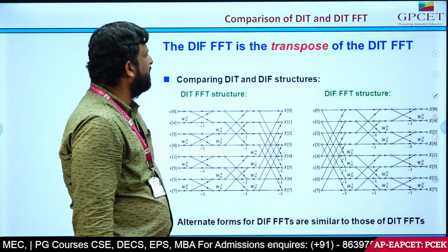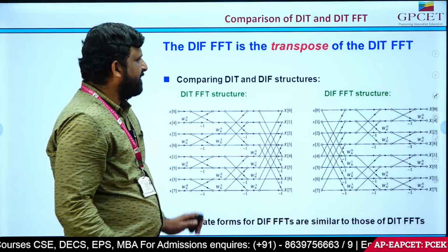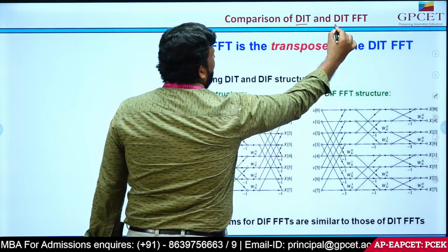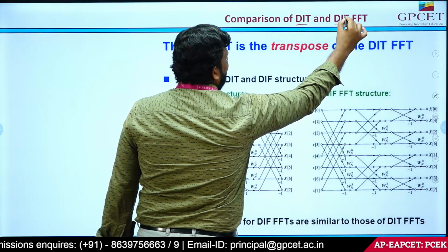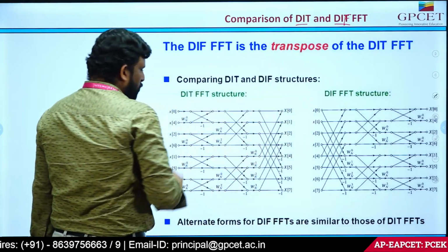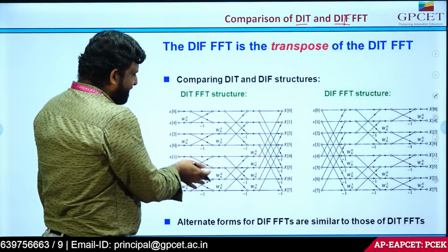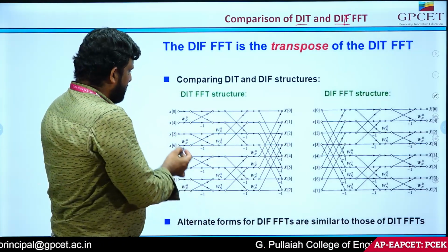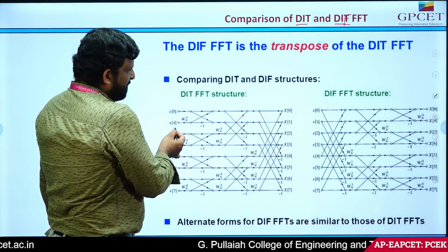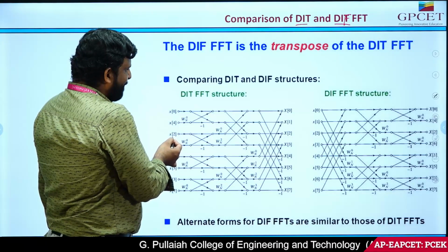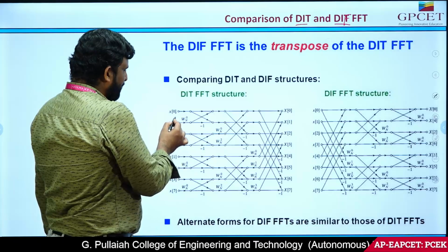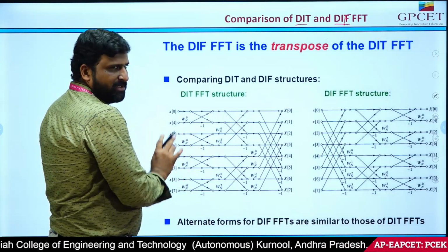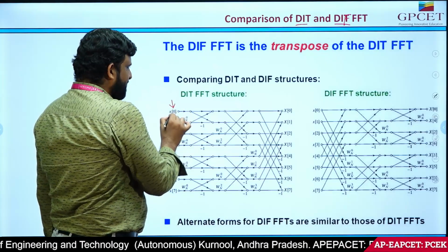So this is the concept of the IDFT and DFT. And finally, I want to show you the comparison of DIT and DIF. See here, two structures I have written, the DIT structure and the DIF structure. You can see the differences. Here, x of 0, x of 4, see the input that I am going to get in DIT. With bit reversal, 0 4 2 6 1 5 3 7. The first difference is bit reversal.